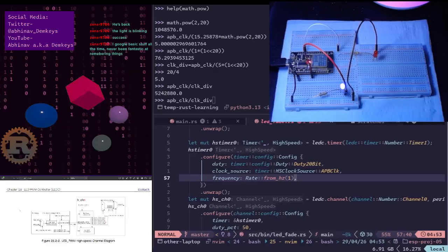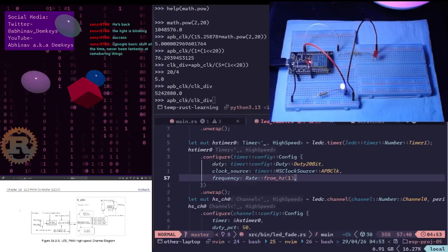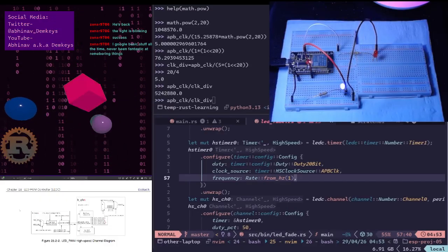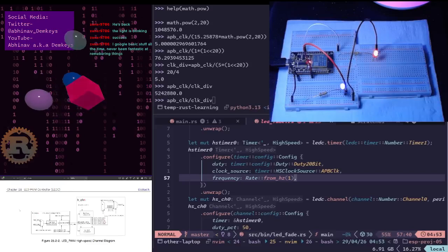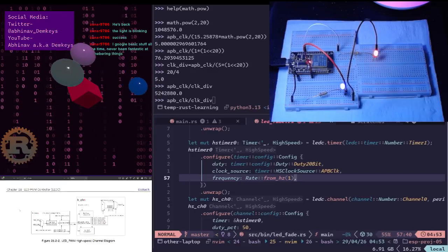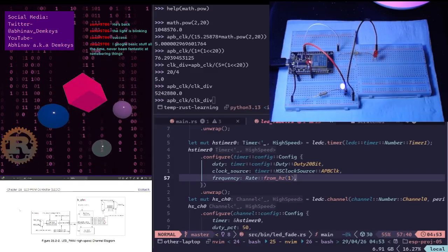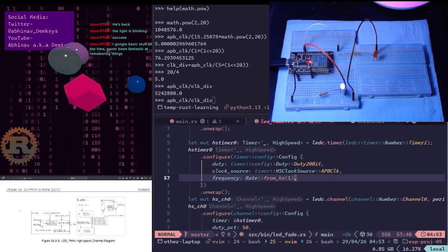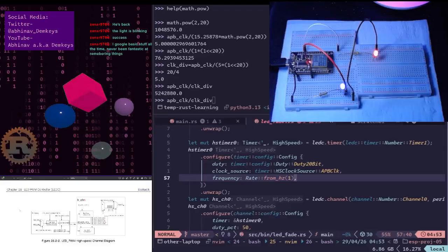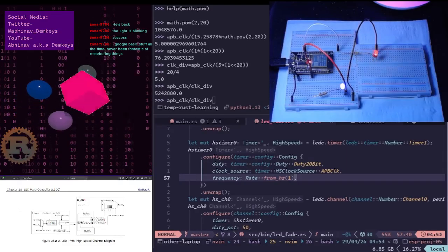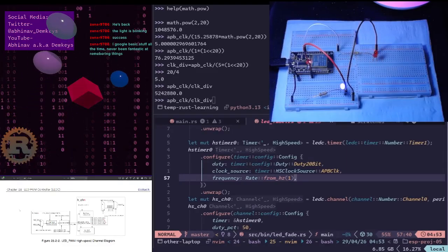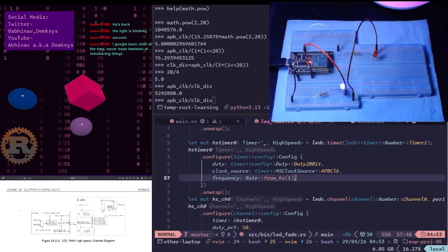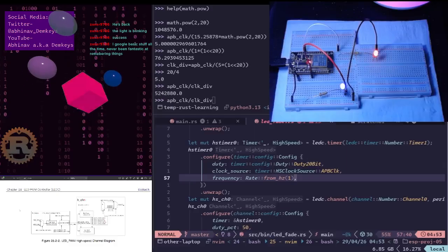Okay, what the hardware looks like inside. Think of the divider as a gatekeeper circuit. The input is the APB clock and the value from your 18-bit register. The logic, a series of flip-flops forming a prescaler. The output is a narrow pulse, also called a strobe, apparently, that acts as the enable signal for the main PWM counter.